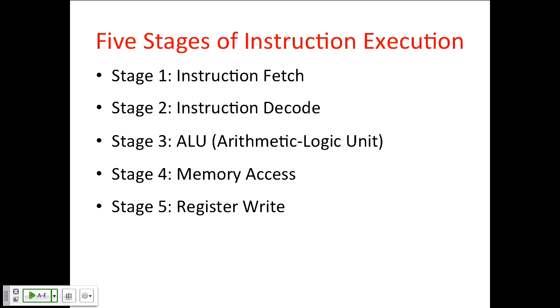Now, in thinking about building a computer, you are all now somewhat familiar with the MIPS instruction set. So those are the instructions that the hardware understands and that it can execute. And in thinking about building the hardware, you first sort of sit down and figure out what are the different phases of executing all those instructions. And for MIPS, it turns out we can break those down into 5 stages of instruction execution. So all the instructions go through these phases of execution in the hardware.